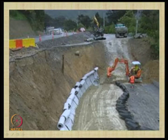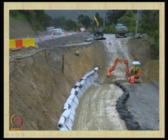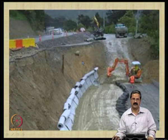Here is another typical example where you have two slopes. If the rain comes, this material is good and this material is good, but at the interface there is a possibility of weaker layer formation. The water should not enter, and finally the new soil that you have placed should not come out. So, we design properly and see that all this is taken care of by proper drainage arrangement, with water at the top going into these drains, and at the bottom a collecting mechanism.